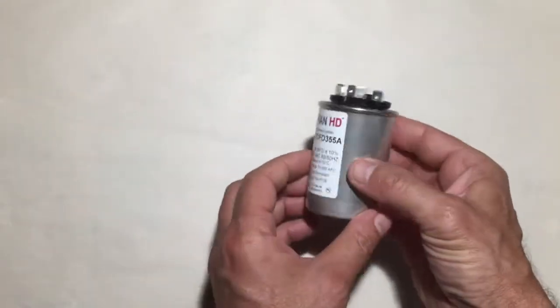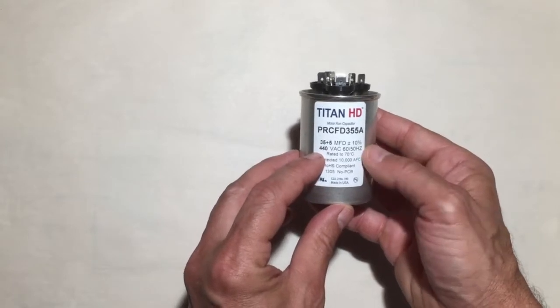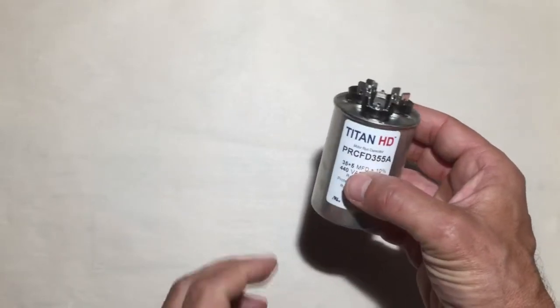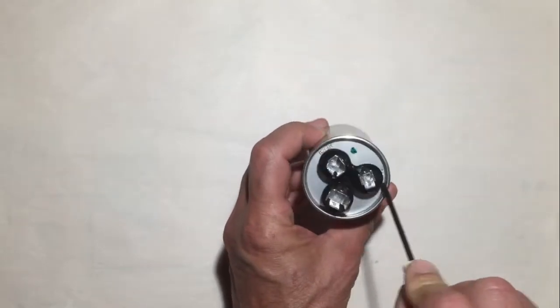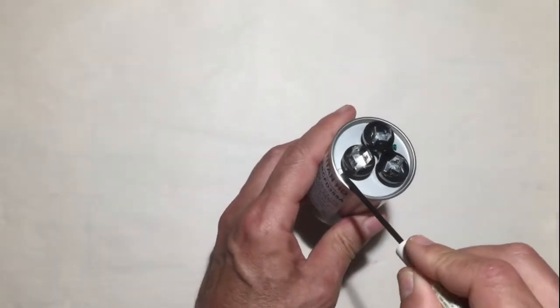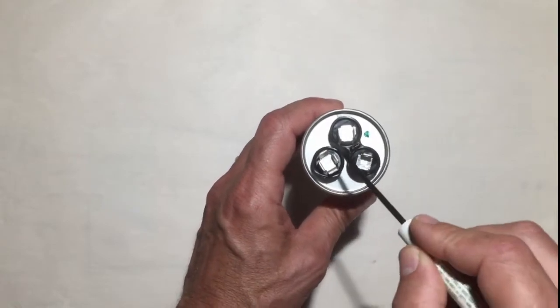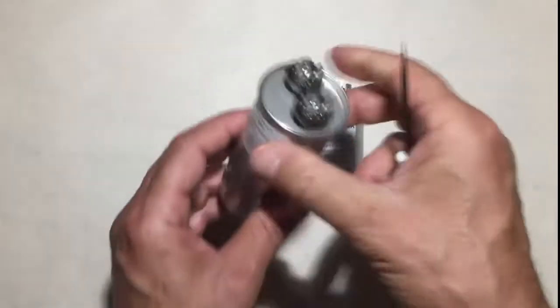So first thing we'll look at is, we talked about the capacitor. So here's a capacitor. Basically this one here, it says 35.5 microfarad plus minus 10, and then 440 volt AC. And then these are the legs that we were talking about. There's the fan connection here. I don't know if you can see it or not, but there's one here. It says HERM, and it's one over here. It says C. These multiple connections here basically allow you to connect multiple wires to it. So that's one. And then the single cap is this one here.